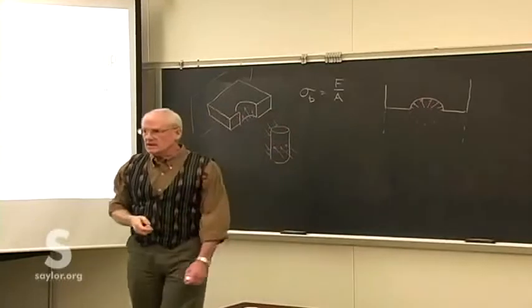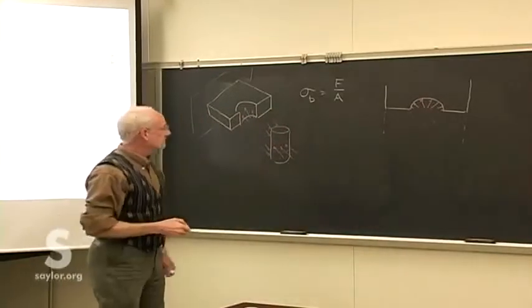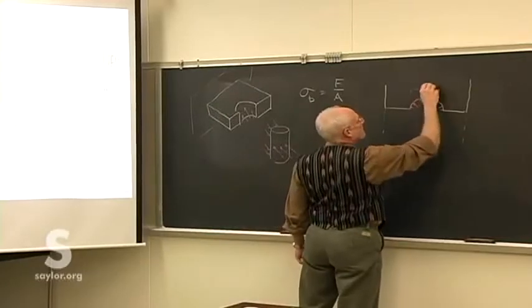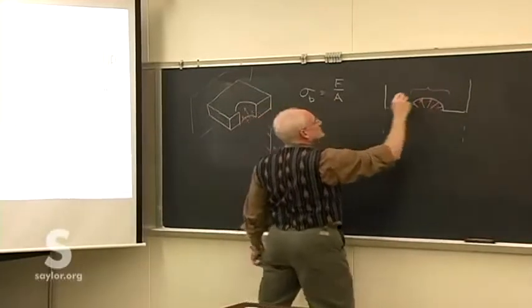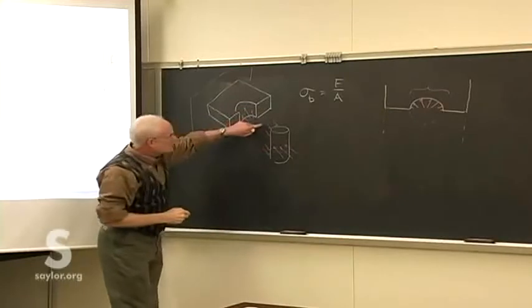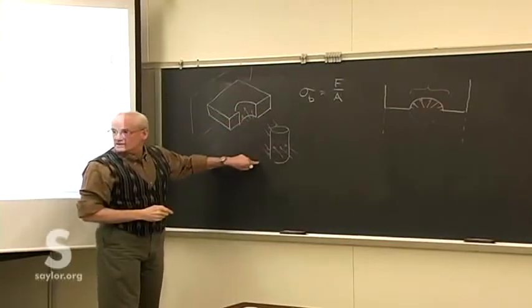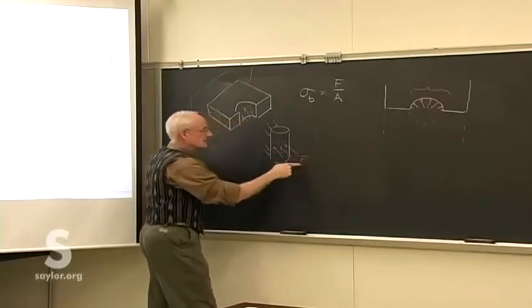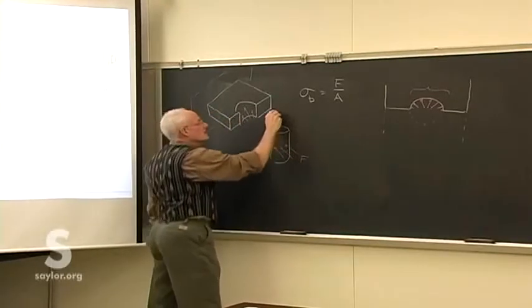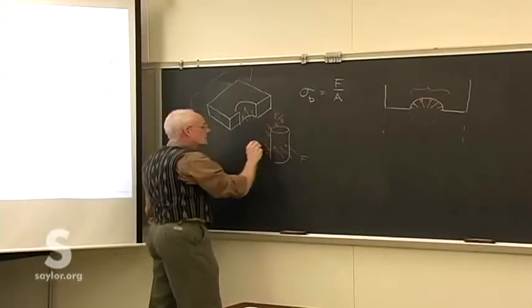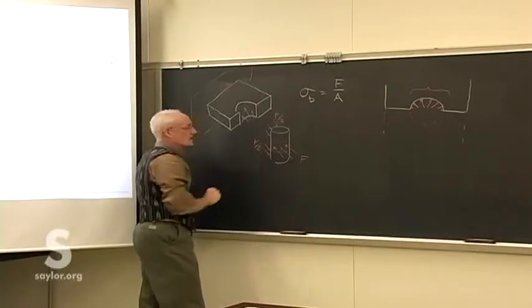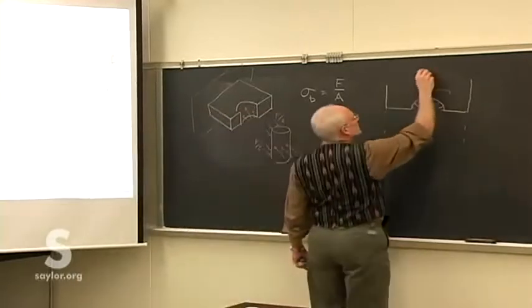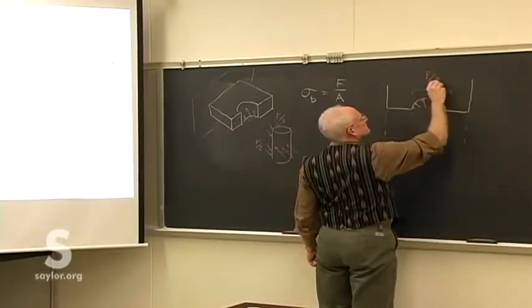We have sort of a circular force distribution where that total force is, of course, actually F over 2 because there's two surfaces where this bearing is going on. This is the force coming from the member, so F over 2 is at the two different bearing surfaces. So this is really F over 2.